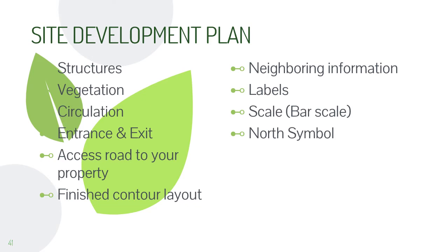Then, the finished contour layout. Not the existing contour layout; that is the most common mistake in the site development presentation. Of course, it is already the developed plan of the site, so the contour layout should be the finished layout as indicated by each location in the site. Later, this will be explained in the site grading part.